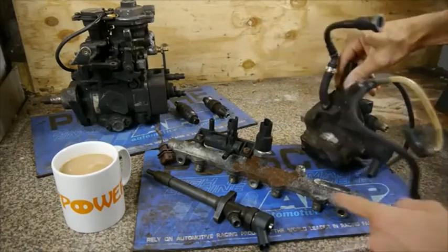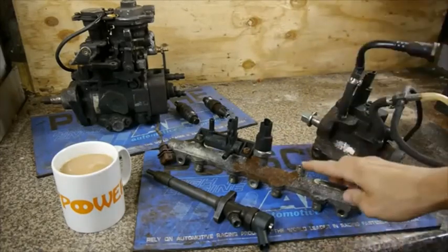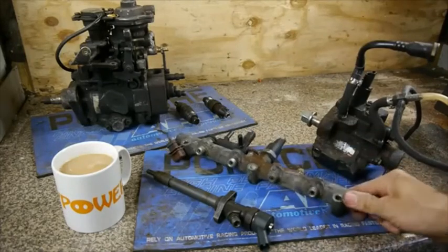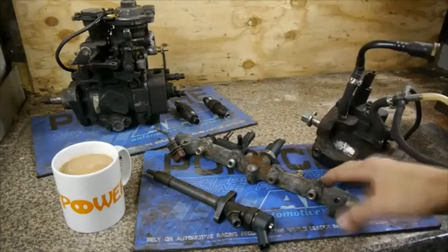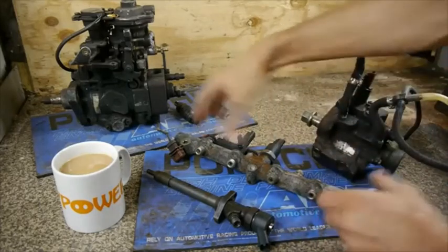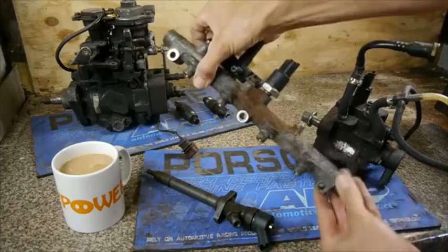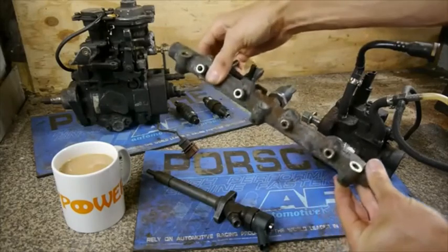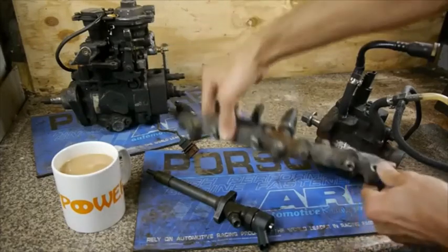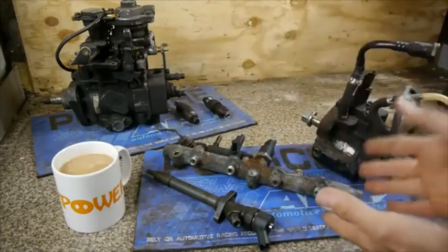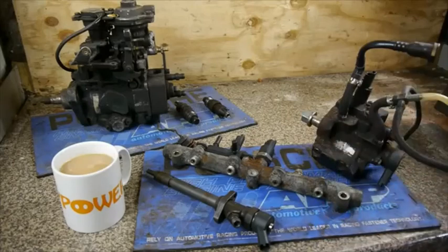This output goes to a point on the fuel rail, which happens to be on here. And then, because this is a 4-cylinder, you have 4 outputs from the fuel rail that then go to each injector. So this injector rail, although it doesn't look much, holds all the fuel pressure, whether that be 1,000 or 1,500 or 2,000 bar or more on modern systems, which is why we get some systems like this called the common rail injection.